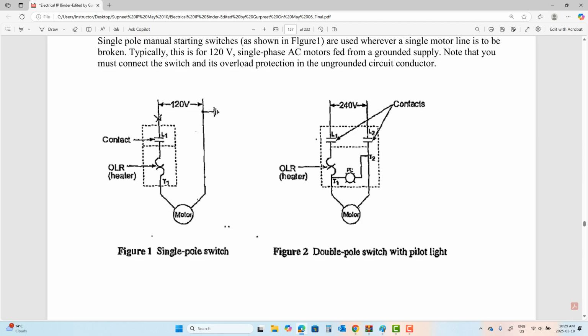In our kitchen, let's say we turn the microwave and the toaster oven on, what happens? On the same plug, after 5, 10, 20 seconds, it trips the breaker, right? That's called an overload device. Why? The plug is designed for 20 amps. If you're sucking up 30 amps, the wire gets heated up, the wire attached to the breaker. Now the breaker is getting heated up.